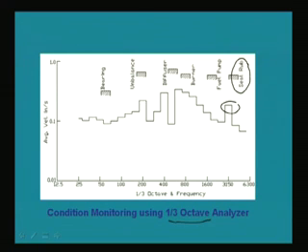So we have some correlation between the frequency and the various components of the machine, like seals. This is of pump, fan pump. This is burners. So various members are there, and they are giving different frequencies. So this is one way of finding the faults in the machine.